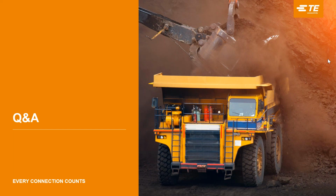I think I understand, if I understand correctly, for a 40-meter channel, that channel can support up to 4 inlines. So that would be 4 connections, wire to wire, and also including a connection to the board on both ends of that connection. So 4 inlines, or a total of 5 specific cable assemblies over that 40-meter length based on the IEEE specification. If the question was related to mating cycles, I think DT high speed with gold-plated terminals is rated up to 100 minimum mating cycles. Good information, thank you.